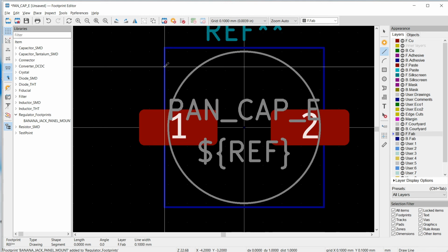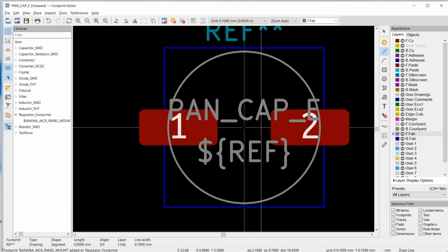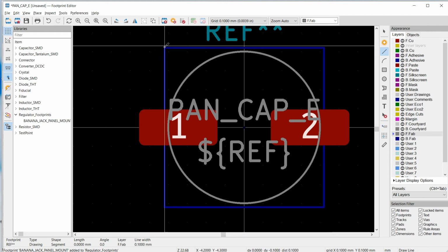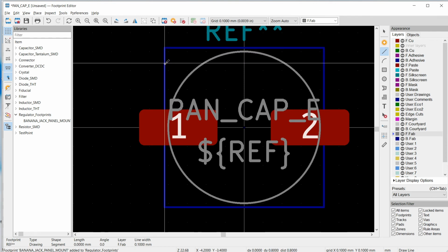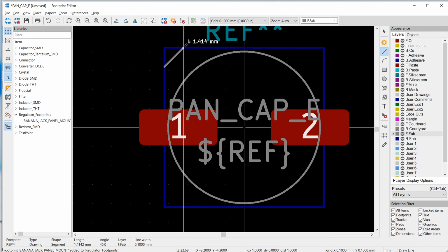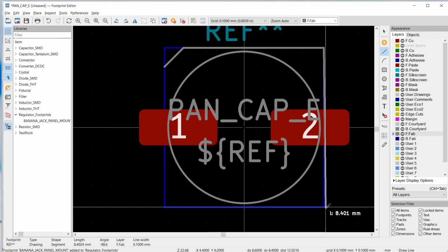To make that measurement, I go up to the corner here and then press the space bar, and that zeroes out these DX and DY indicators down here. So now I can look at the change between where I zeroed it out. So we'll come down here 1 millimeter, and then now in the DX we're 1 millimeter, and then we'll just match this outline all the way around.